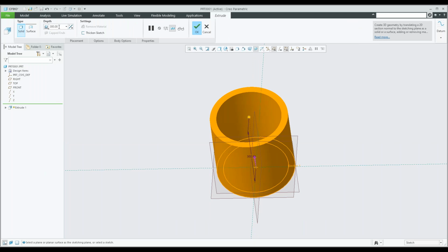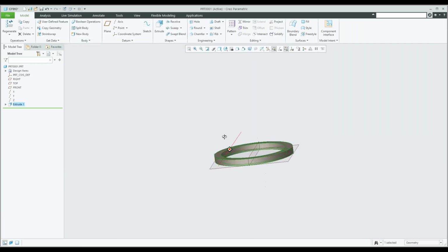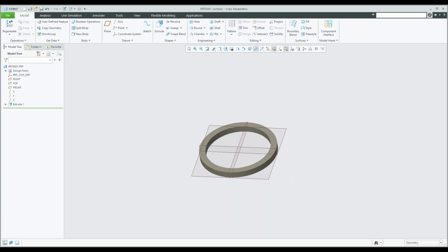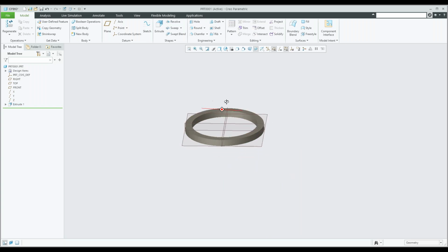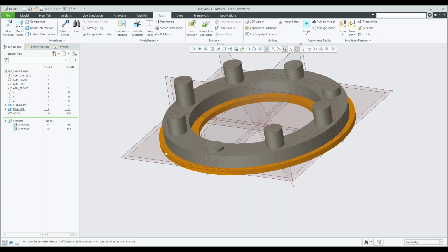I didn't record the last one. I stopped that too early. So that's 3 values. It should have taken the thickness as well. Okay. So the point is that you can use things like that to make your life easier to create things. You can do the same for holes, but I want to take the hole one and I want to move that to the UDF feature that I wanted to show. So let's go back to our assembly. Yeah, I'm going to open up this component.